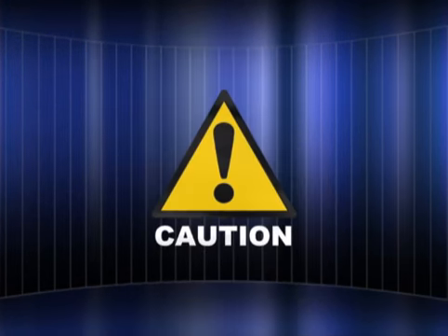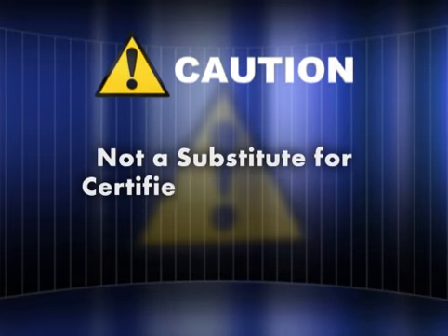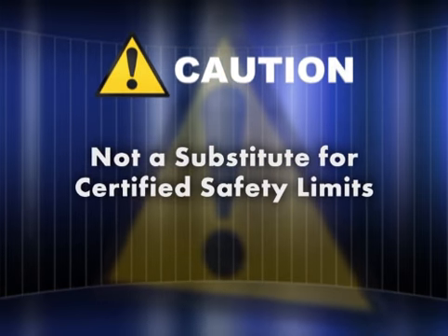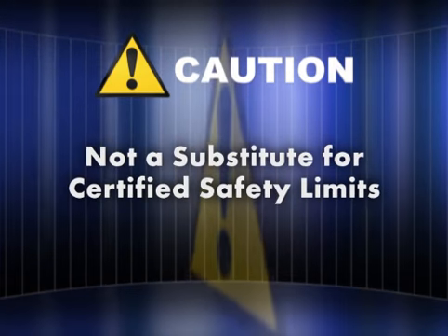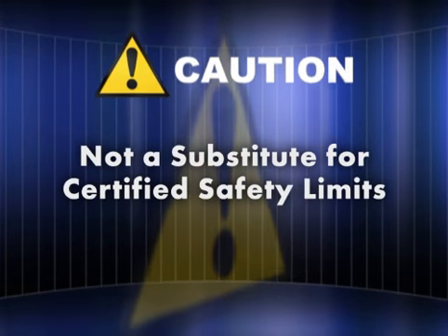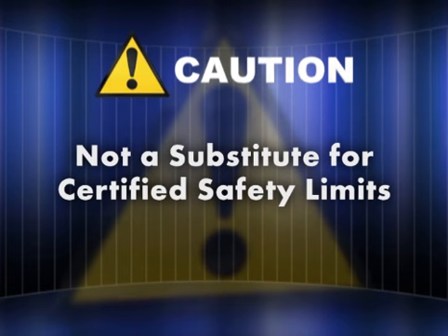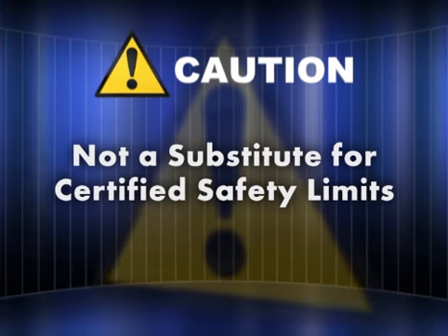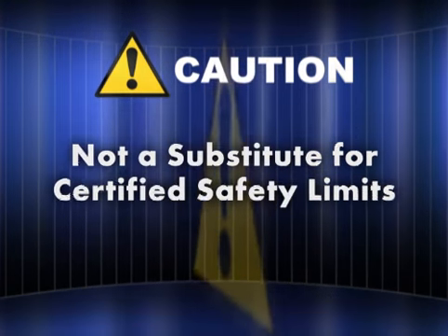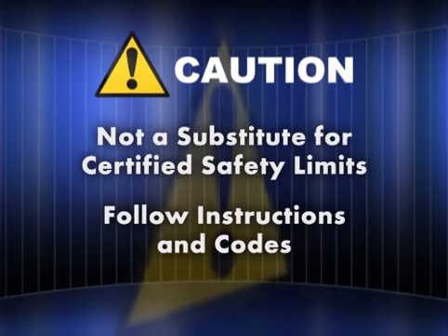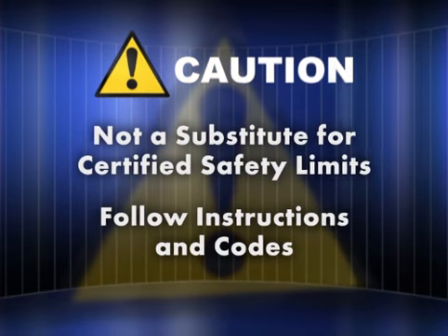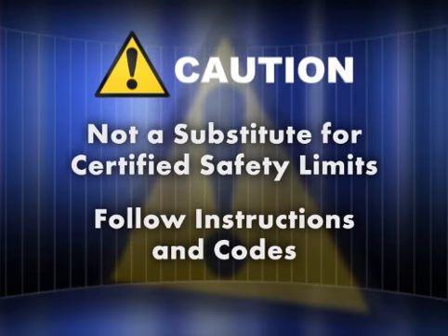Improper installation and operation of outdoor reset controls could result in damage to the customer's heating equipment and/or personal injury. Outdoor reset controls are not intended for use as the system's limit control and must not be used in place of an aquastat. Additional controls certified as safety limits must be in place in the control circuit. Always follow manufacturer's instructions and install controls in accordance with all applicable codes and standards.